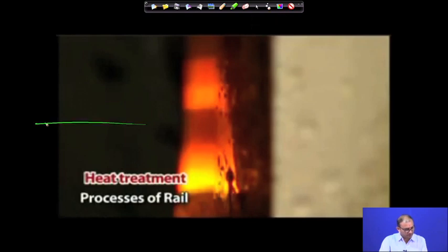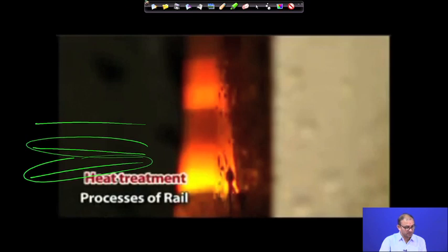So, this is our required line, but if your guide has some type of problem in this direction when you are manufacturing it, even if it is only a few microns, it will create a lot of problems. So, straightness is more important. We will see that many different processing steps are performed only to make sure there is straightness between the layers.